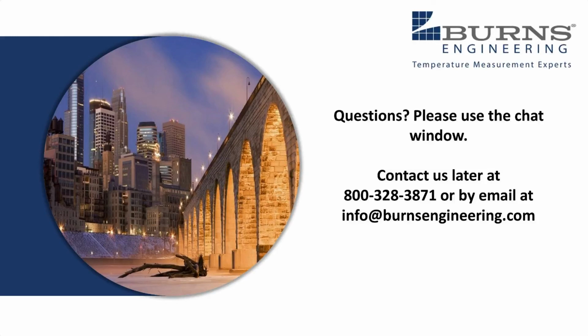Yeah, that's a good point, because we'll use water, but of course other materials are going to respond differently. Even at the same flow velocity, they could be wildly different. I have noticed that, especially in the food and beverage industry, where the process material has a really high fat content, you can put the probe in there and it's going to have a much slower response time than in just water.